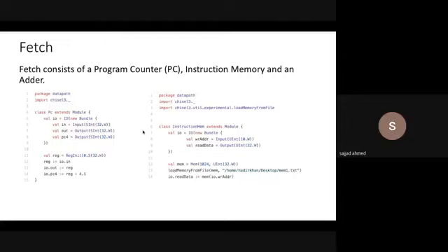Then moving downward, there is a reg. We create a 32-bit register using the RegInit construct of Chisel. Chisel provides many variants of registers, including RegNext and RegInit. RegInit is comprised of the global clock and reset signal. In Chisel, clock and reset are global signals; you don't have to explicitly define them. Then in the next line, the register is getting input through io.in and then giving the output to io.out.